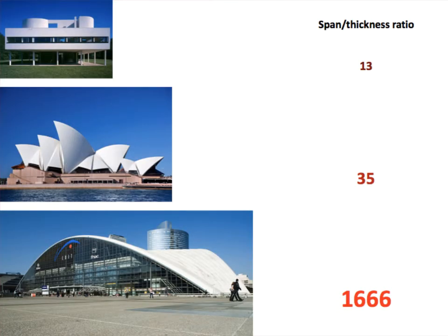In the context of the horizontally spanning structures required for architecture, the most significant factor that influences the best compromise that will deliver overall economy of means is span. The longer the span, the greater is the level of complexity that is justified in the pursuit of overall economy of means. The parabolic form of the CNIT shell was fully justified for a span of 200 meters.